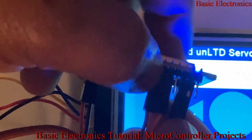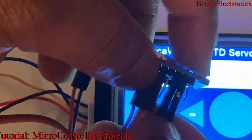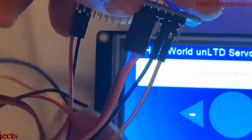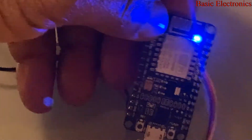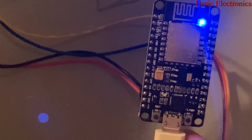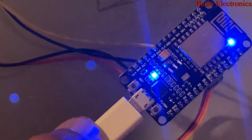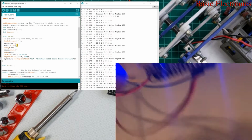So we moved the transmit and receive pins to other locations, GPIO 4 and 5. Alright, so that's why we modify this. So everything looks cleaner right now. And then we'll have everything plugged up on this NodeMCU. Great. Alright, so that'll be it here.